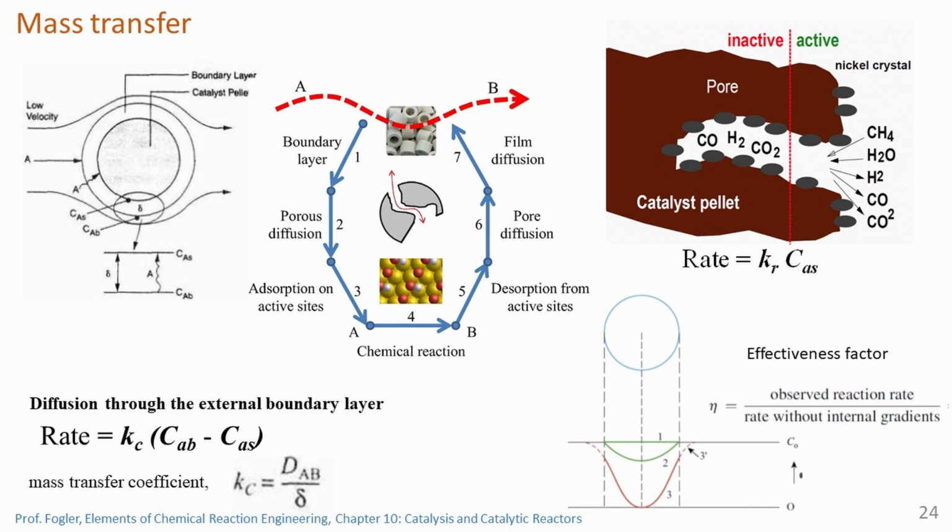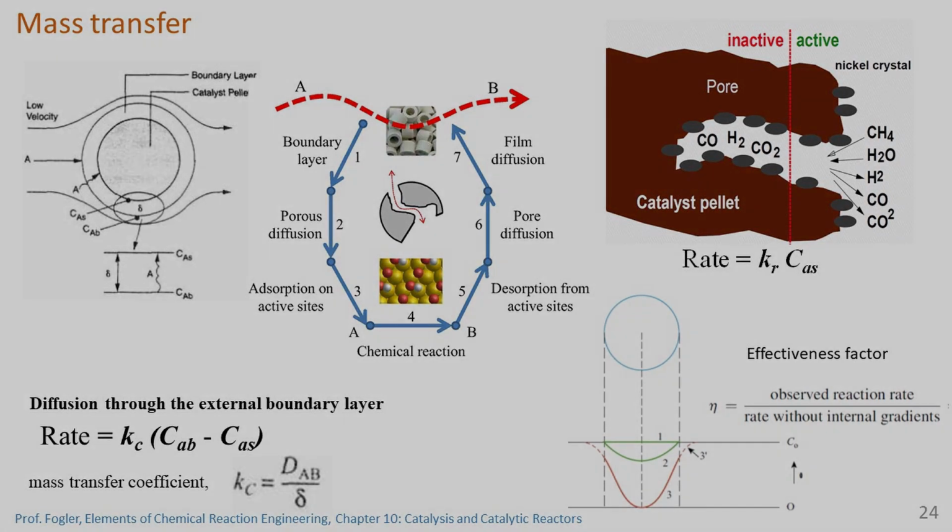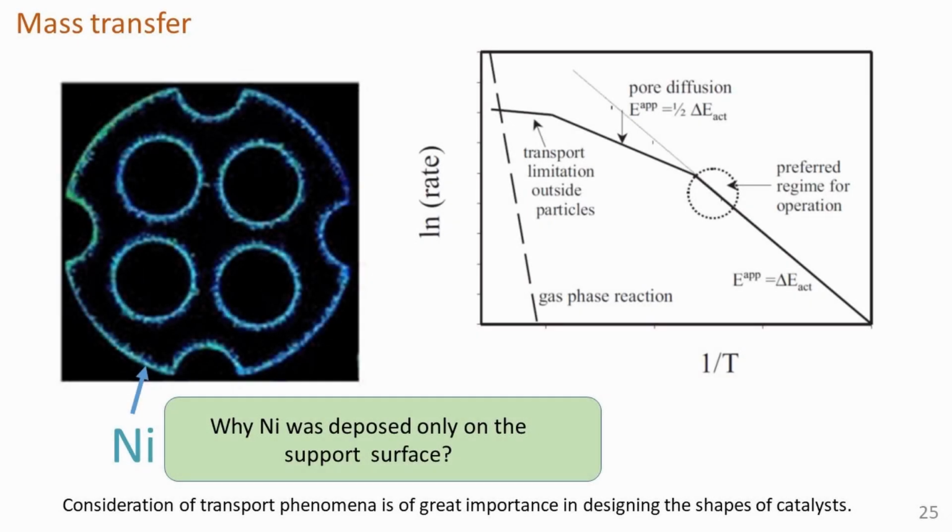In case the internal diffusion effects are significant and there is no external mass transfer resistance, then the concentration profile would vary across the catalyst pellet. In all reactor types, the desired conversion takes place on the catalyst. Side reactions, such as carbon formation, are eliminated by use of the proper catalyst type, controlled catalyst bed inlet temperature, and a given steam to carbon ratio depending on the type of the feed. The role of the catalyst in all cases is to achieve equilibrium conversion while maintaining low pressure drop.